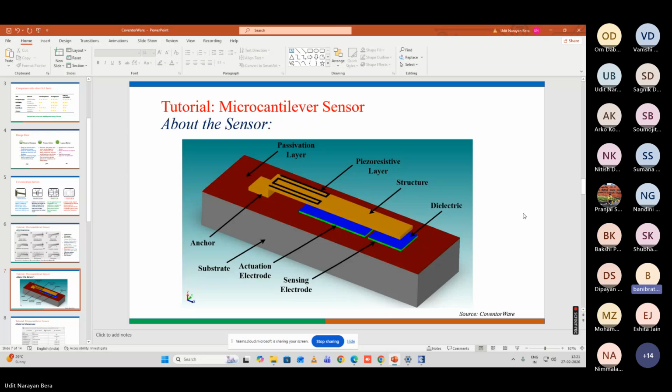So from that perspective, we come up with the stiffness parameter or the mass parameter for an individual element. Then for the whole cantilever, I assemble all the individual components together to get one n cross n matrix to do the analysis. For that purpose, the very popular numerical method used for analyzing these kinds of devices is called FEM or finite element method, where we segregate the whole cantilever into a finite number of individual elements and do the analysis for each individual element. Later on we assemble the whole analysis together to get the complete solution, right?